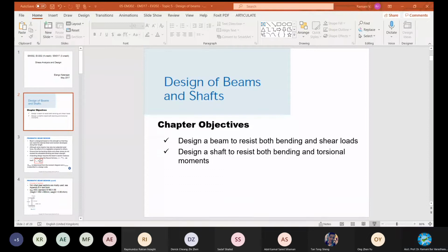non-prismatic section. Why are we not taking non-prismatic sections into consideration? They are all non-linear. It is very difficult to model or analyze them using the simple arithmetic methods or static equations that we are using. For proper design, you really have to go through matrix analysis using MATLAB or software like STAAD Pro. Only using software can you analyze the failure pattern thoroughly so that the corresponding design is appropriate.